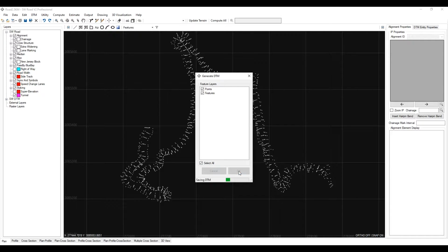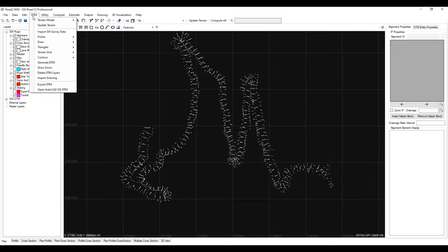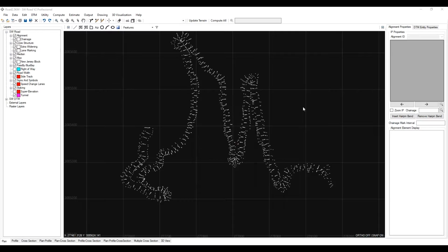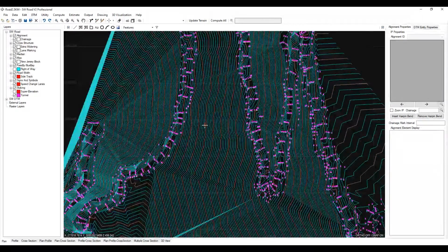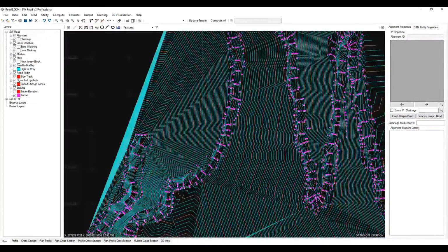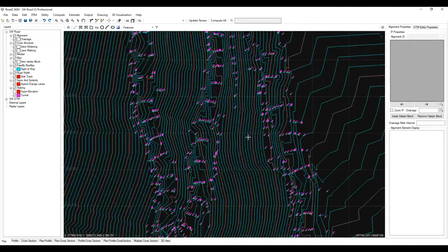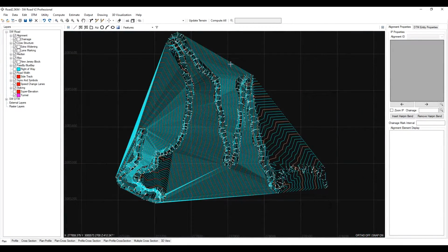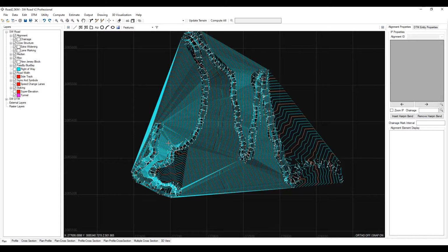Let's just select all for now. Okay, here it is saying that DTM is generated. So click on contour, draw quick contour, draw. Here you can see our contour is created, but if you have noticed one thing, the contour is jumping from here to there, but in the real field we don't do like this. So we have to mark certain boundary over this surveyed road.